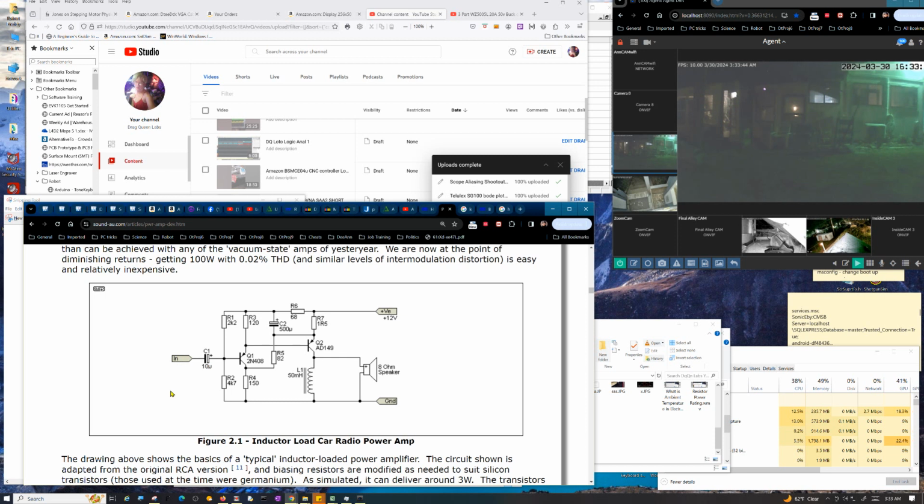So that means when the voltage is lower than 8 volts, you're fine, but when it goes above 8 volts, well, it's a short circuit. So there's that. And if it's got enough power to it, it'll damage your capacitor. It may even damage it even if there's not much power. Again, I'm still apprehensive about using capacitors that way, especially if I wanted long-term reliability. But anyway, in theory, you can get away with it.